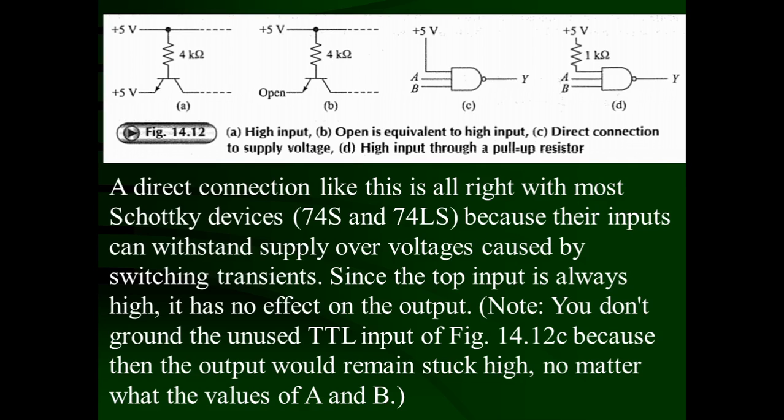What happens now? When you switch on the power supply, then there is a transient voltage is going to be generated, and that transient voltage will not be exactly 5 volt, but it will be higher than that, and then after it is going to be regulated. That means transient spike voltage which may rise very fast and will be dying out very slowly. So there is a brief instant of time where the voltage is going to be more than 5 volt or 5.5 volt.